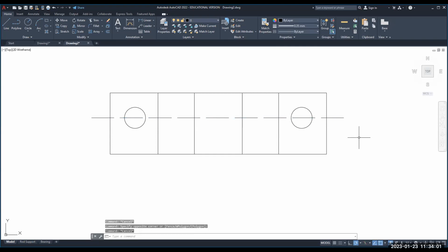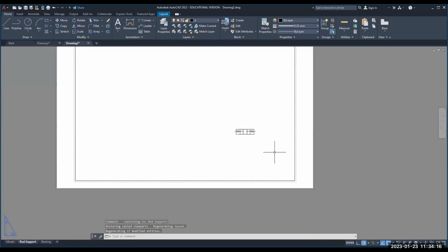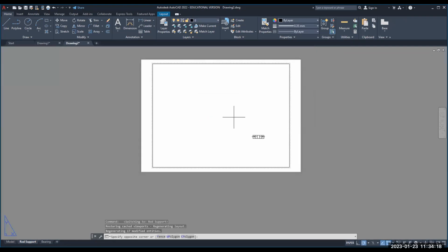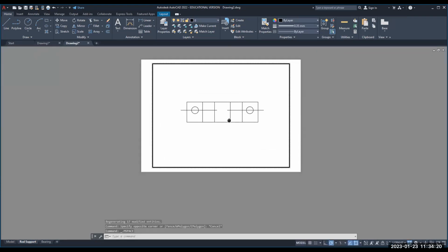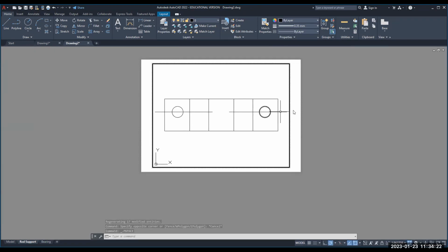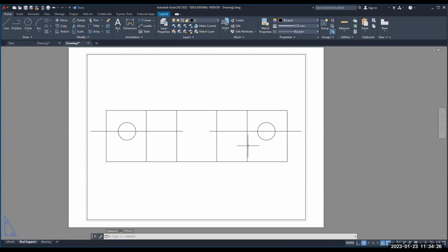Yeah, it really should be the thickest line in the drawing. For the visibles, you have to go thicker. Just make sure you can do that. All you really want is a clear difference. But definitely go into the layout to look at it because it'll look different in layout. Like look at my dash lines in layout.